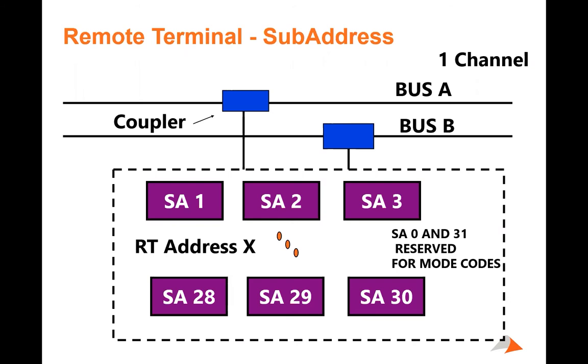Then you would specify how many of those words you would use for the message, and it always would start at the first word slot and count out. So if you specified 5 words, it would be the first 5 words. If you specified 20, it would be the first 20. Strangely enough, in the actual 1553 word, if you specified all zeros for the number of words you want, you actually got 32. That's a little thing that people have a problem getting straight in their minds.